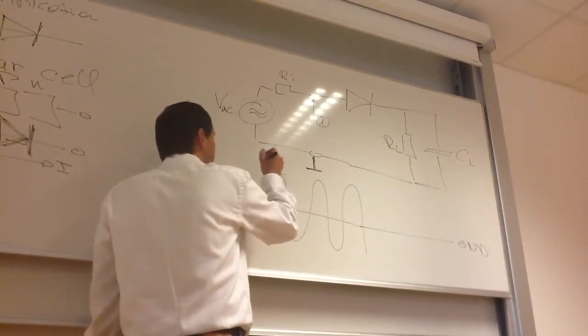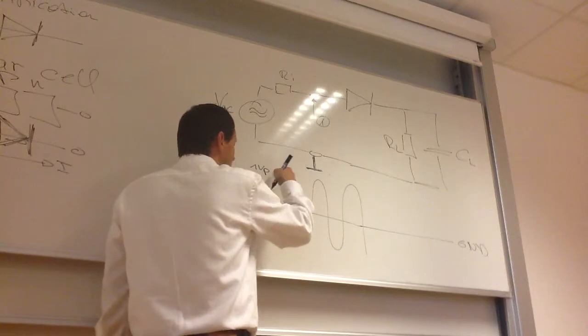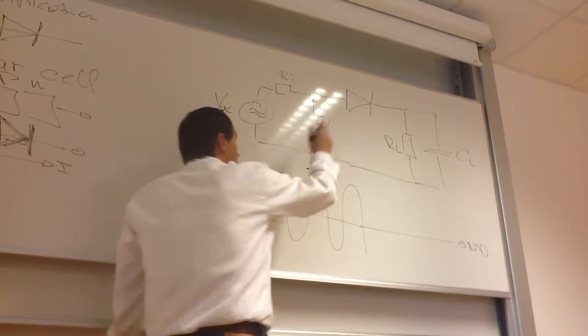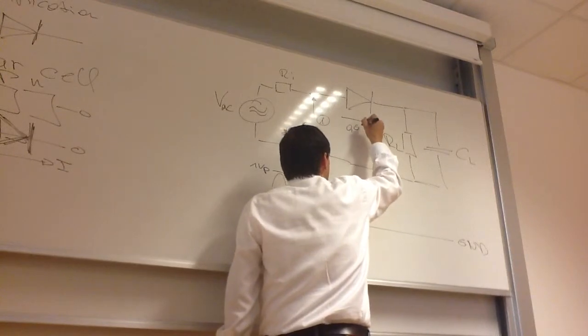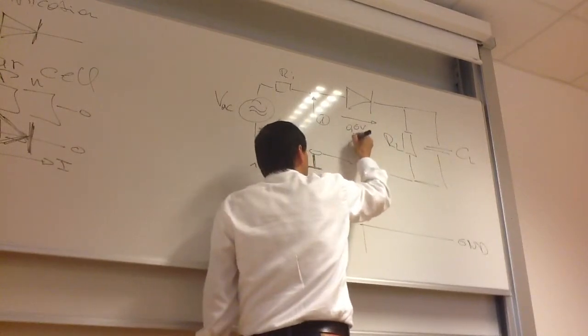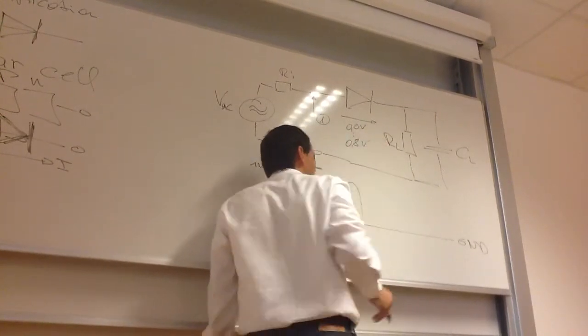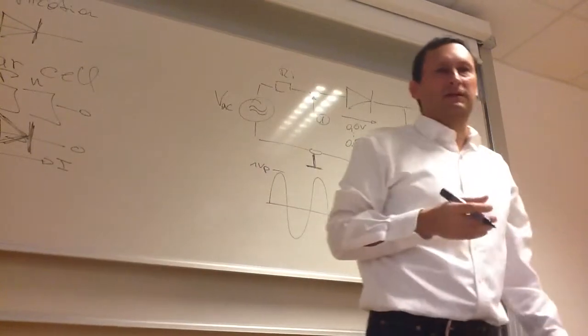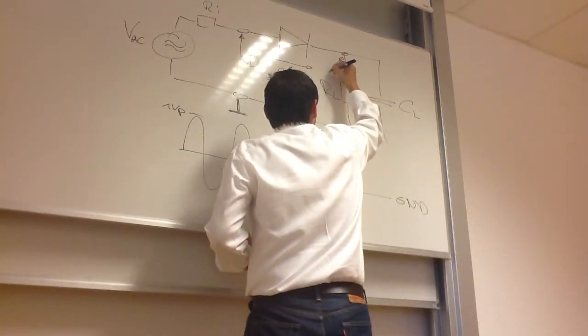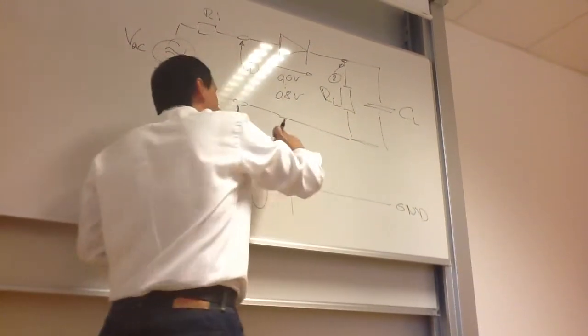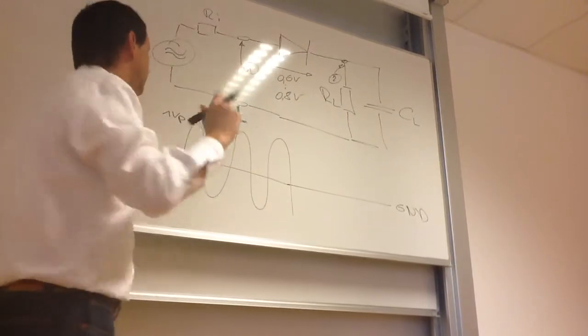That means if we have 1 volt peak here, across the diode we roughly lose about 0.6 to 0.8 volts. It depends on the current flow. So on the other side here, if we put the probe in now here, we lose 0.6 volts.